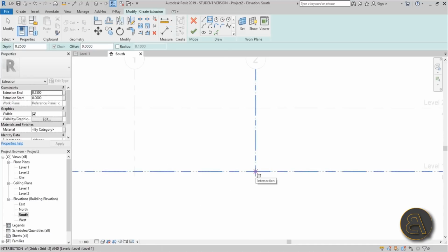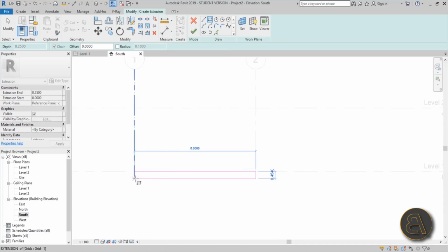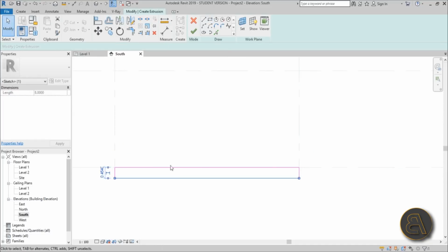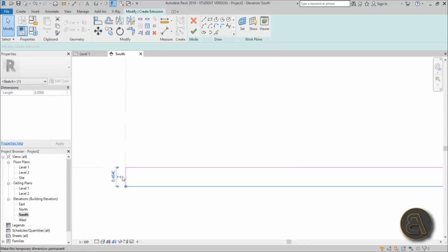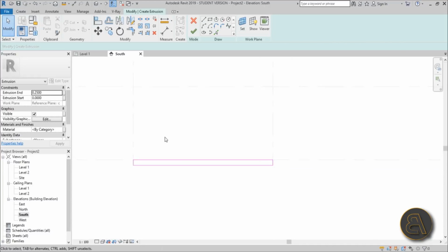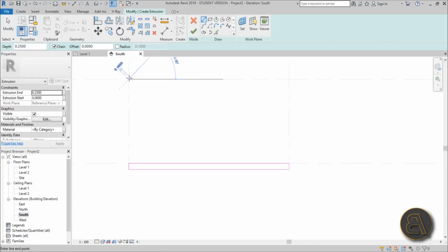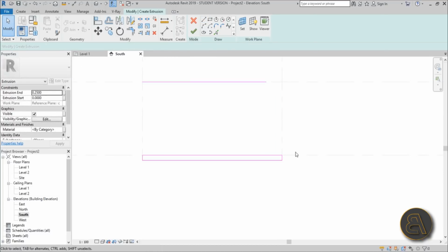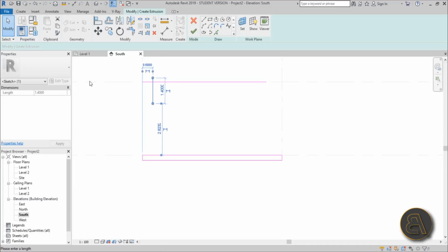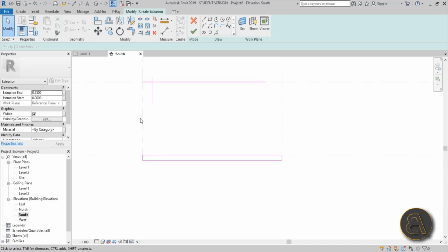Now it's kind of hard to see it like this because it's a bit too white, but anyway, you get the point. Let's just delete this, I don't need it. Okay, so for this, let's set it to 0.3 meters. That's 30 centimeters. That's just the base of the thing, and here this is the top part, and now we need to create that arc that we have on this thing, and I want the arc to finish, let's do 0.6 meters from this edge to have a bit of an uncovered edge.